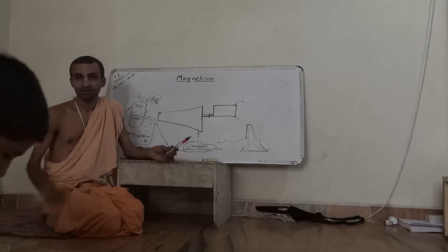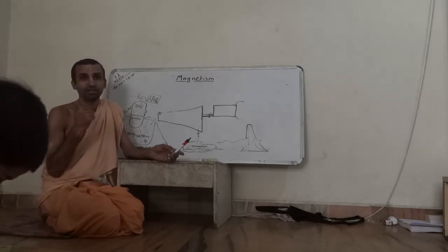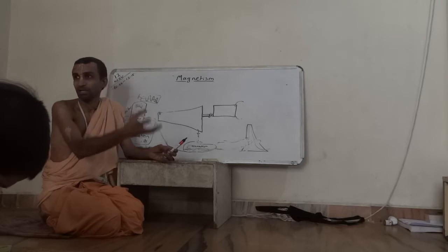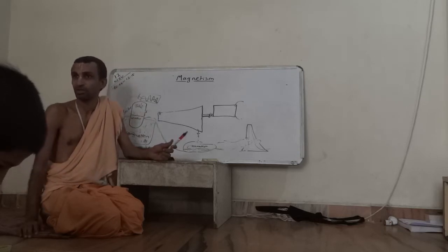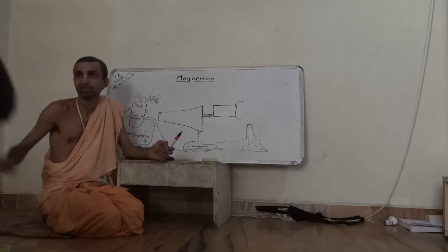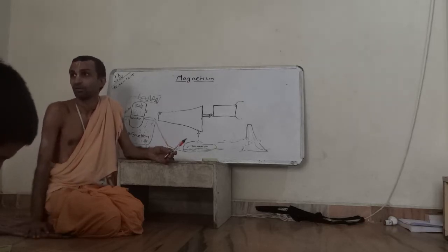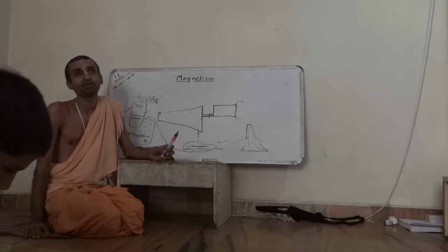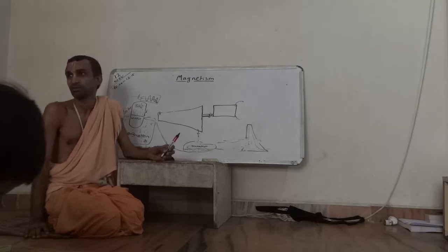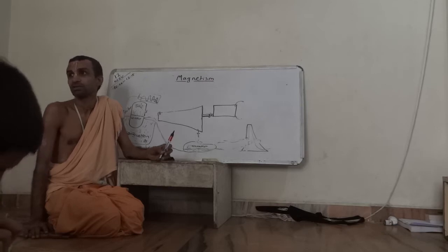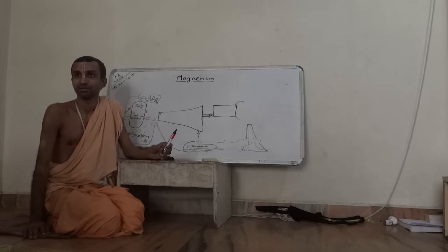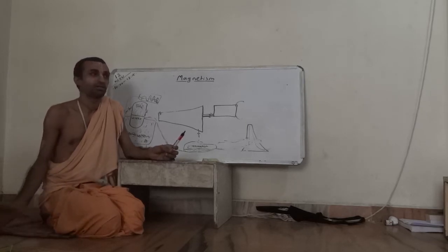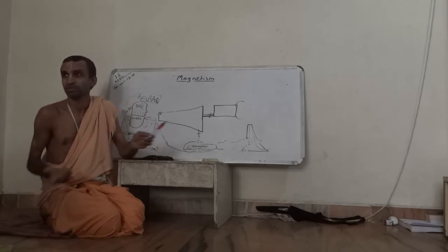So the point is that in anything, the energy which you apply, the output you will get is a little less only because of losses. Energy will be lost at some places. Temperature loss is there, frictional losses are there. So efficiency means if you apply 100 units of energy and you get 80 units as output, then you have 80% efficiency. If you supply 100 units of energy and you get 50 units of output, it is 50% efficiency.